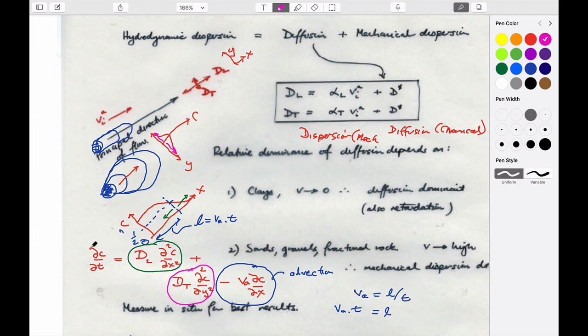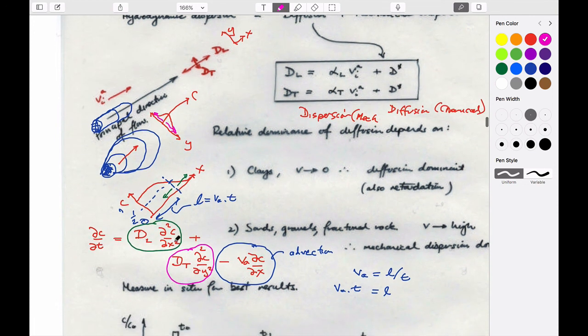And so it's important that we use things like conservation of mass and Fick's law and advective fluxes to be able to define things quantitatively, which is this expression at the bottom. The net accumulation rate of solute is equal to that removed by lateral spreading, longitudinal transport by diffusion, transverse transport by dispersion, and the advective flux. And we know exactly what these physically look like in terms of their behaviors. So that's kind of the crux of what we'll deal with today.